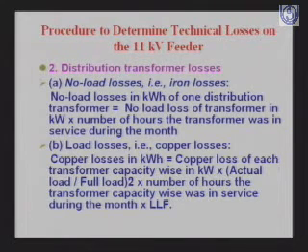There is a confusion in your book. I think full load should be taken here as a peak load. Then square of this into the full load copper loss, and the number of hours the transformer capacity was in service, and this is to be multiplied by the loss load factor.